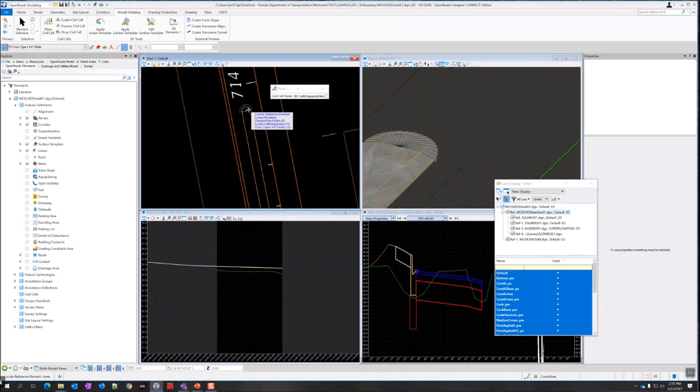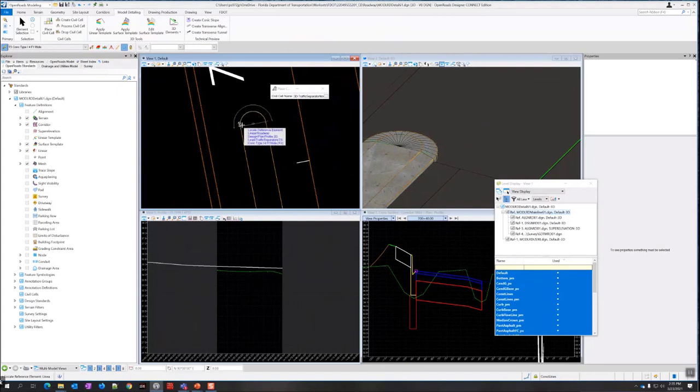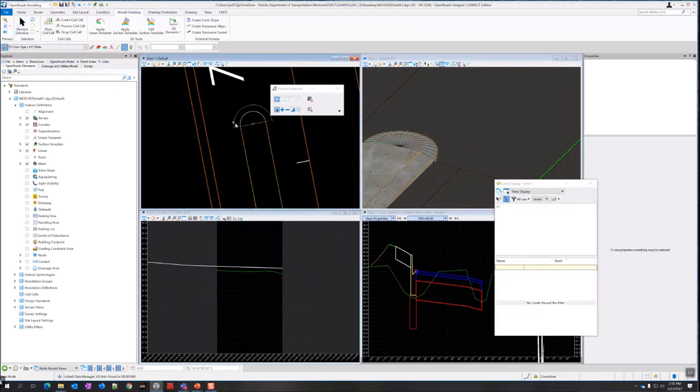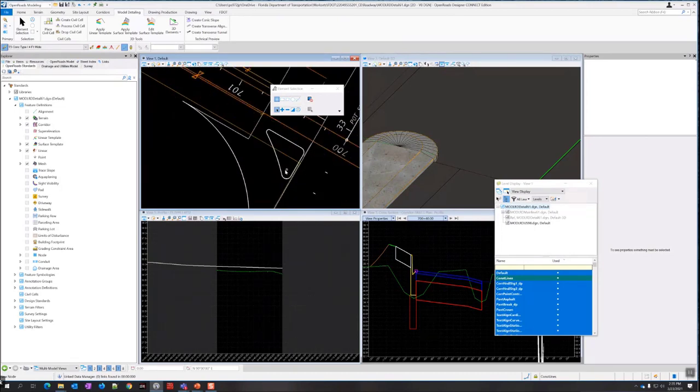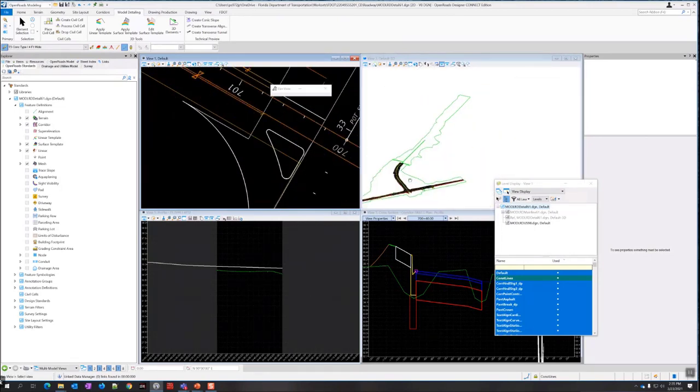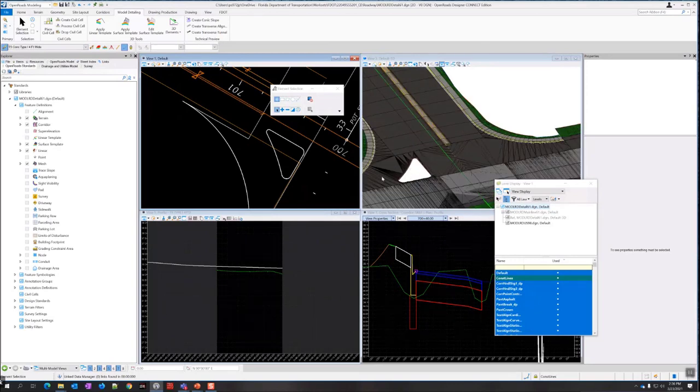It's in there. So you can see a few extra handles in the 2D. So basically, this civil cell has a linear template built into it that runs the traffic separator around this little arc. All right, so it's there. Now we just need the right turn island. We need to build a linear template for this to put in curb. All right, so we're going to go to the model detailing tab. This is exercise 4.11. So model detailing, we go to apply linear template.